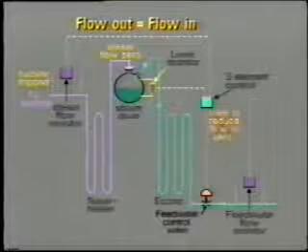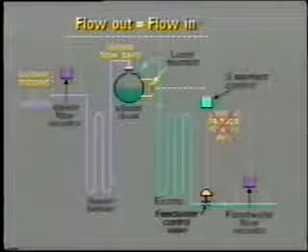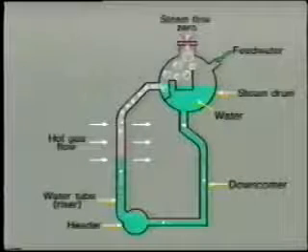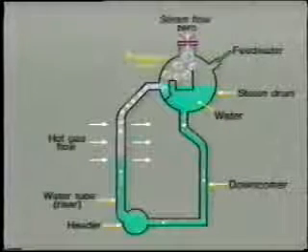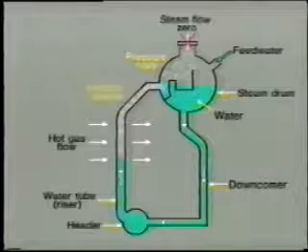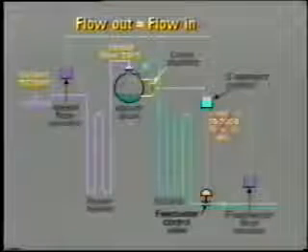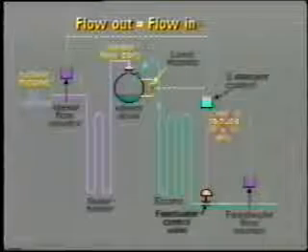However, this is exactly what it should not do under these conditions. Why is this? Well, as soon as the steam flow ceases, the water level in the drum falls rapidly. Why? Well, with higher steam pressure, the steam bubbles which are in circulation in the water collapse. This is called shrink. As the water level falls drastically, the drum level monitor will override the flow elements and open the feed water control valve so as to admit more water.